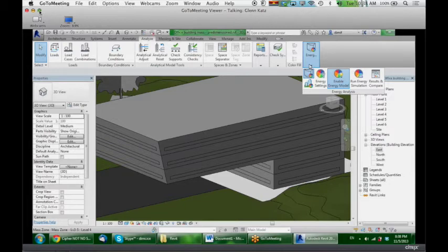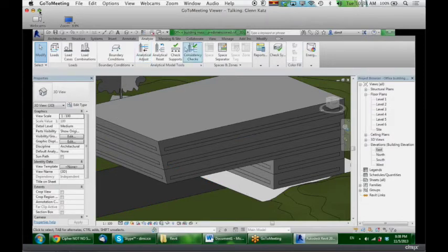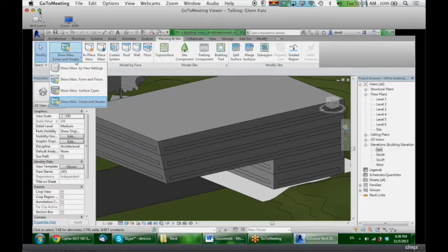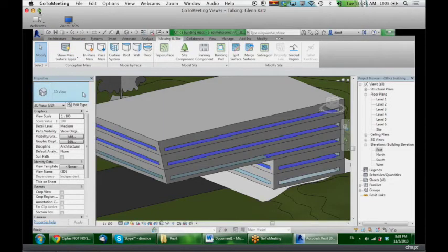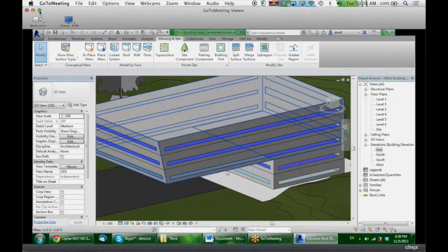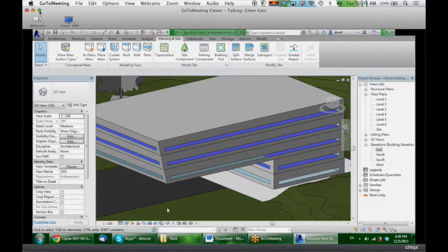Yeah. The idea with this is really, for a lot of things we do in terms of very quick analysis, it actually is sufficient just to say it's about 50% window, 50% wall, and as we think about heat flowing in and out through those different surfaces, you get some pretty reasonable numbers. They're definitely within the ballpark of where you need to be to at least understand comparatively, is this a better shape versus that shape?